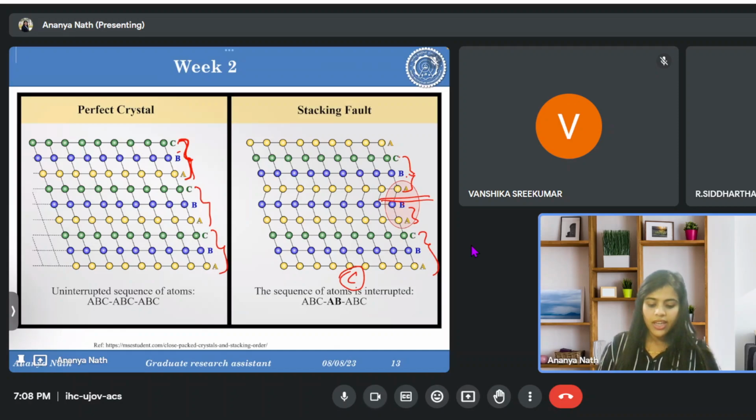There will be a difference in the shear modulus of the solute and the parent atom, due to which the dislocations find it difficult to move. Also, due to the edge dislocation and addition of solute atoms, the shear modulus decreases, and dislocations go towards the lower shear modulus.